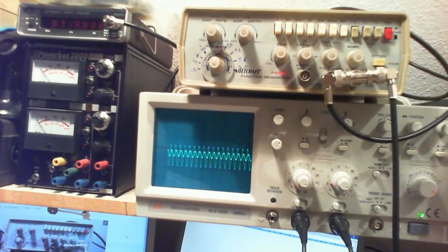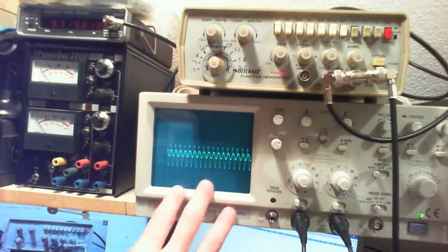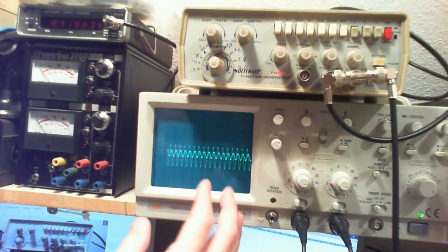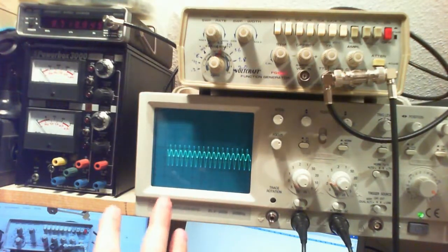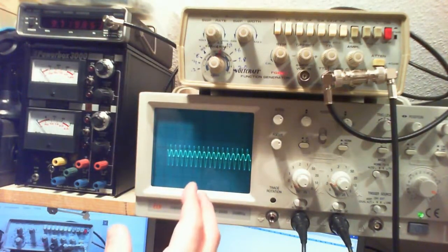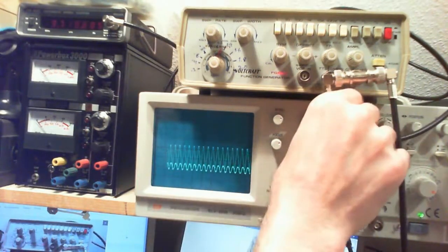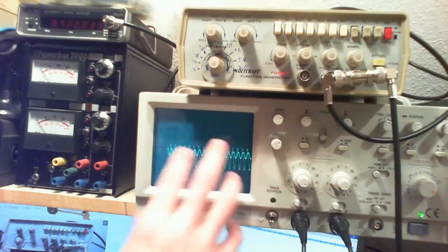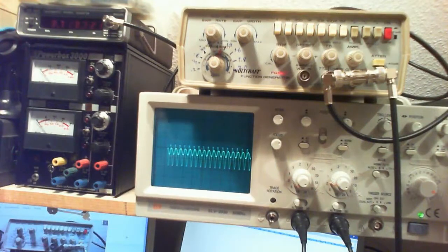Now, before we wrap this up, above 1.3 megahertz there's some sort of weird behavior of this circuit, where the output is actually lagging, because the output is supposed to be leading in this circuit at least below 1.3 megahertz, and also above 1.3 megahertz your output starts diminishing.